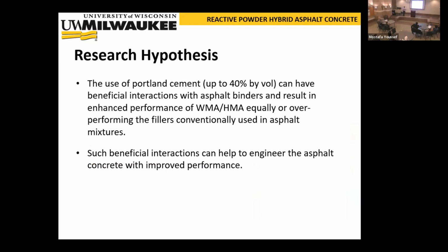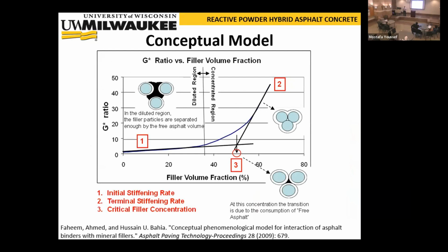We have some challenges in doing that, so we had to think about these challenges as we designed the experimental program. The biggest challenge is that as you introduce particulates inside the asphalt, a viscoelastic medium, you will notice that the stiffness of your mix or blend will continuously increase in this manner. Within what we call the diluted range, you still have enough medium for these particulates to move without causing significant chemical or physical interaction on the binder.